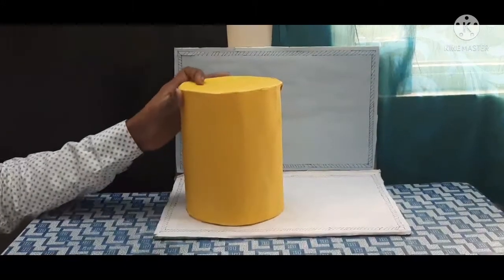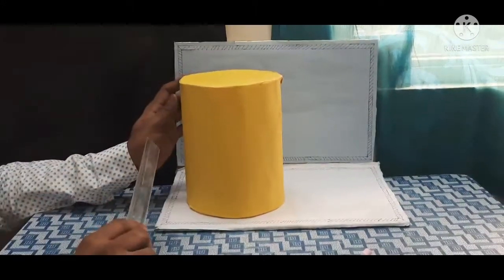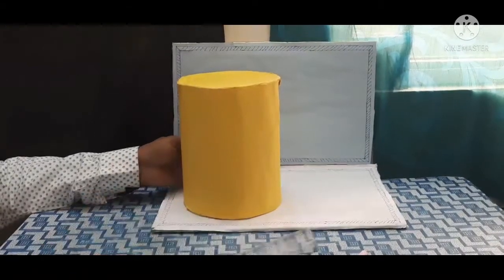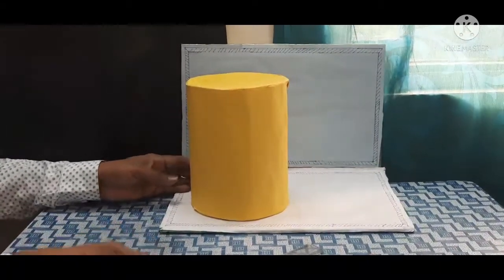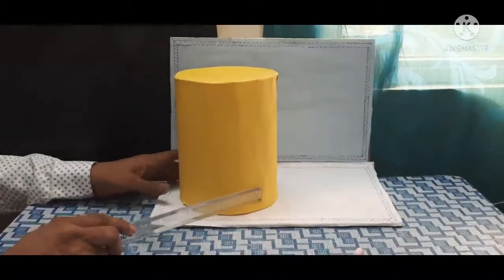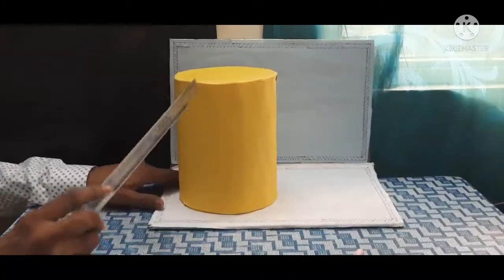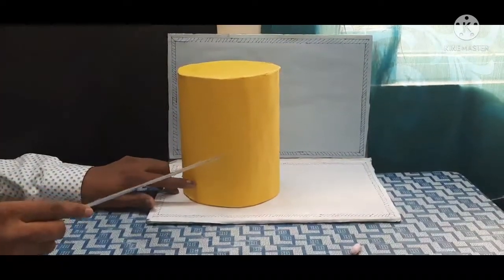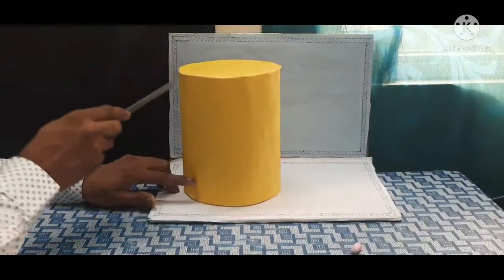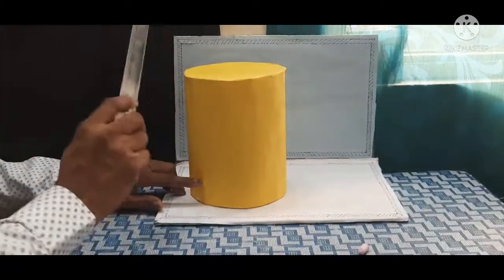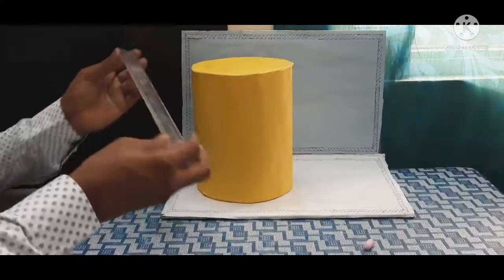Then we are going to do the usual method for cutting. We remove the top portion, and then we can draw the corresponding projections. So this is the cylinder, and for this particular position it is a type 1. First step, you need to draw the top view of the cylinder. Then you draw its front view in the vertical plane. Third step, I am going to cut the cylinder by some section plane.